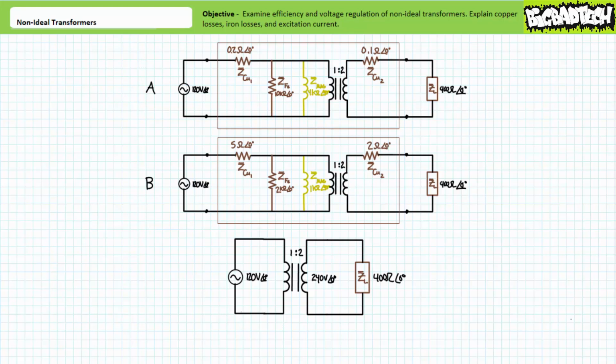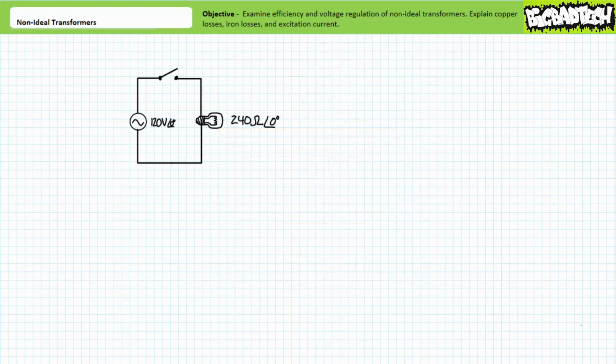At efficiencies approaching greater than 95%, oftentimes, you're more than justified in skipping all the complicated series parallel circuit analysis and simply assuming the transformer is ideal. Before we move on, allow me to comment on the efficiency of non-ideal transformers during no-load conditions and expound upon some of the approximations we made earlier.